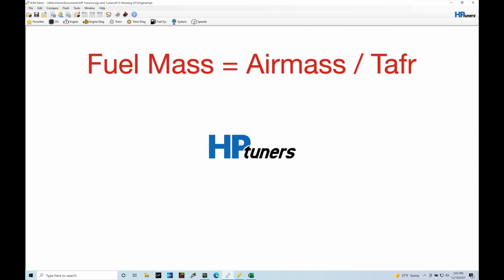Now, if you don't know how to spot bad injector data and bad trends, if you're putting in injector data supplied and things are off, it's very easy to see those kinds of deviations and try to absorb them into your mass airflow curve, essentially skewing what your reported air mass is going to be. That is going to be a temporary solution, but it's going to start to open up a can of worms.